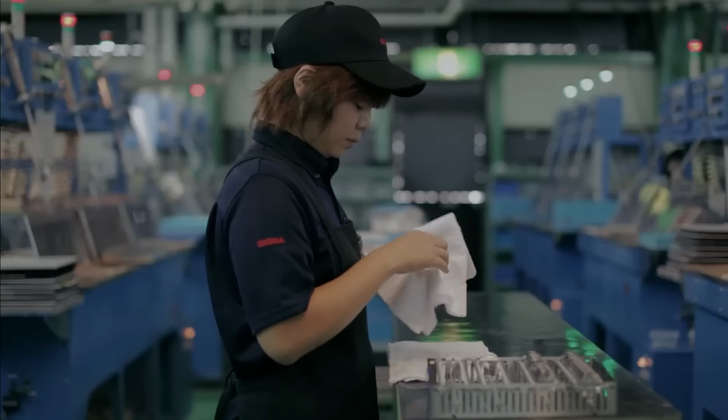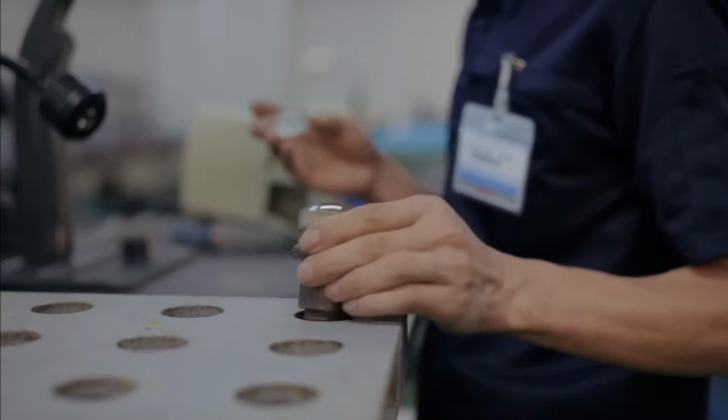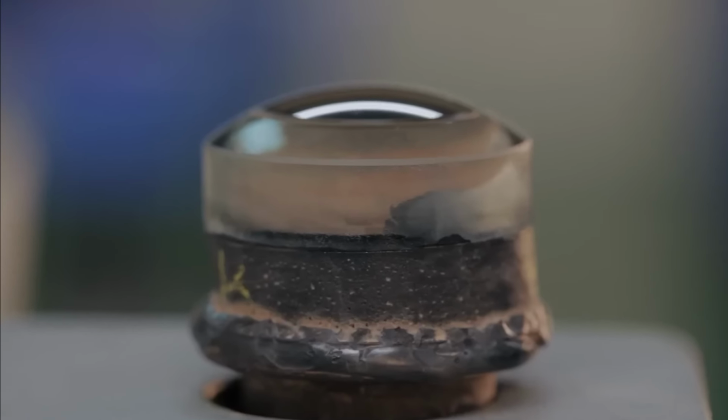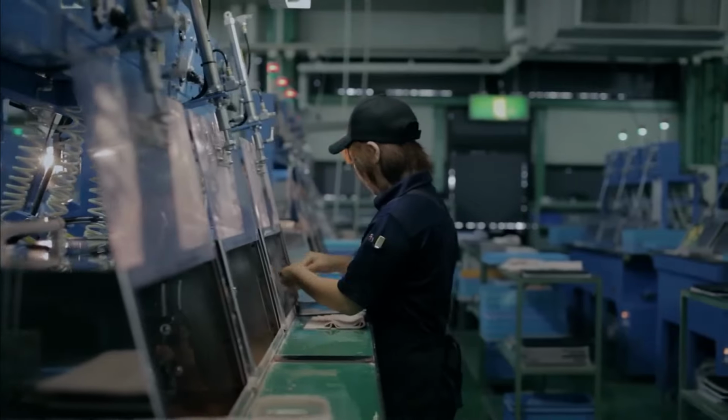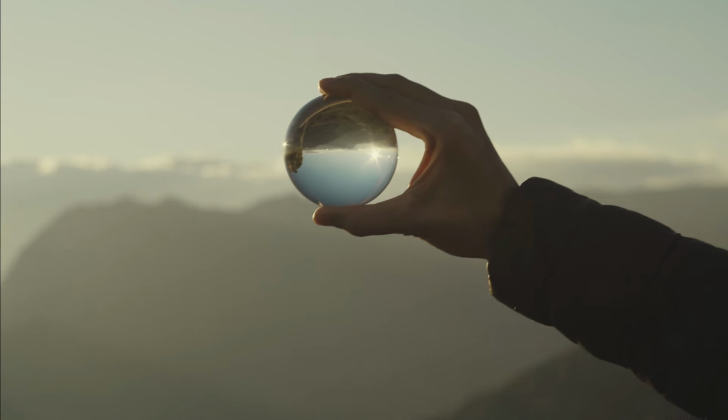A small coating of pitch, wax, or coarse cloth is applied to the polishing tool before wet rouge or other mineral oxides are used as polishing agents. Glass polishing is a lengthy process that involves oscillating lenses back and forth against a revolving polisher for hours at a time. This procedure results in lenses that sparkle, have smooth surfaces, and have flawlessly curved profiles.